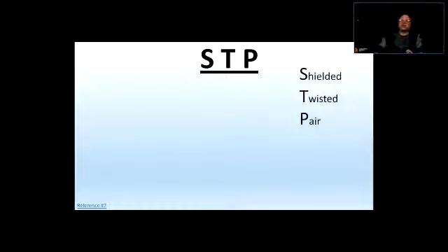So that interference produced by the machinery can actually interfere with the data transmission. So in this case, you need not only a twisted pair, but we're also going to provide a little bit of outside screening or electromagnetic protection, so the interference doesn't go through the shield.